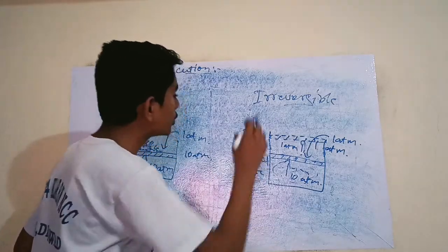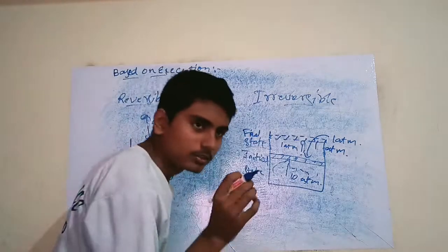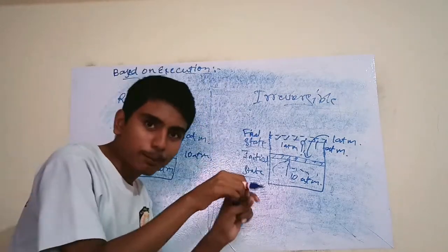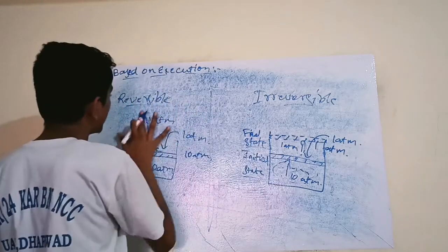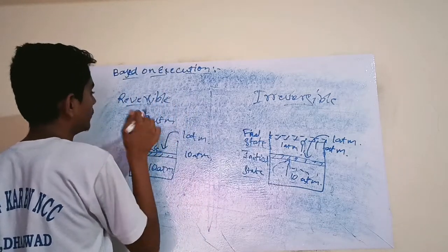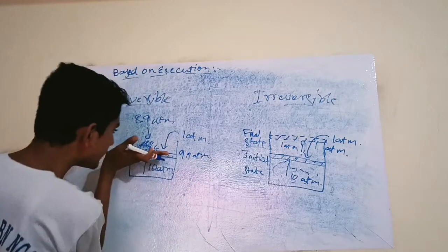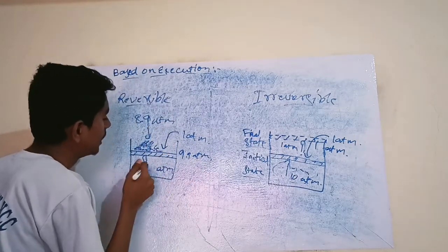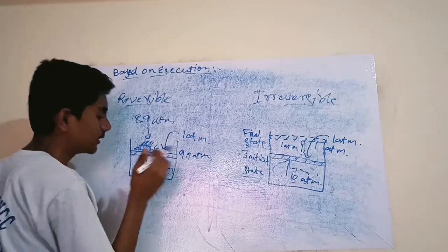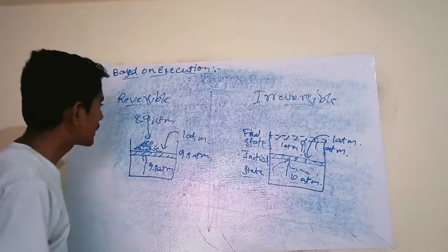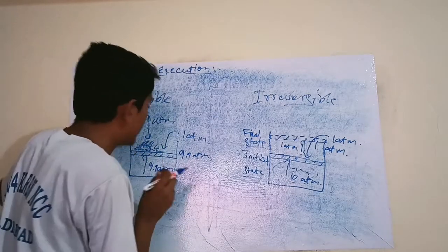Now you don't remove all the sand suddenly; you remove one particle. Now I have picked one particle, meaning 0.1 atm I have picked. Now it will become 8.9 atm, and the total pressure becomes 9.9 atm. Now the piston expands a little bit, such that the gas expands and the lower pressure also becomes 9.9 atm. Okay. Now this state is defined.